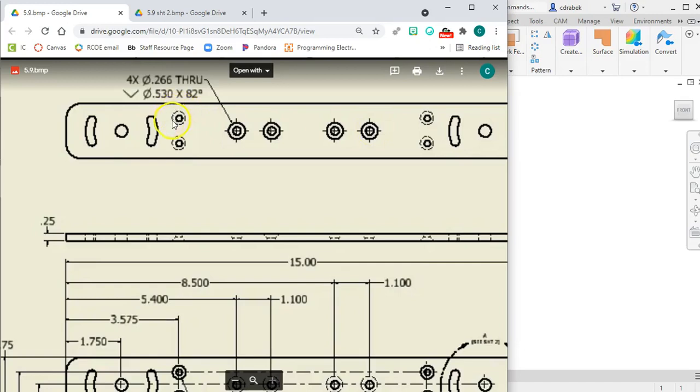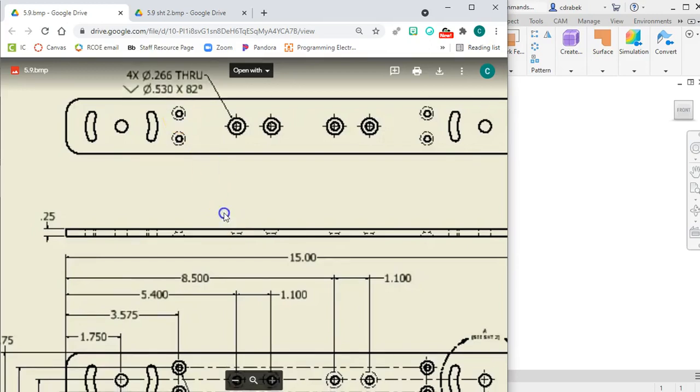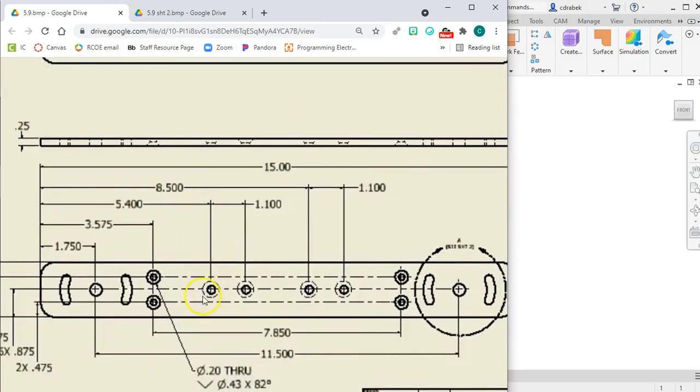And you'll notice that on this side, these four outside ones now have a dashed line around here. Well, it's a hidden line. It's because you can't see it from this side. You can only see the little part that goes through it. So just like here, these are hidden lines because you can't see them from this side. But if you look at your side view, you can see which direction they're all on.